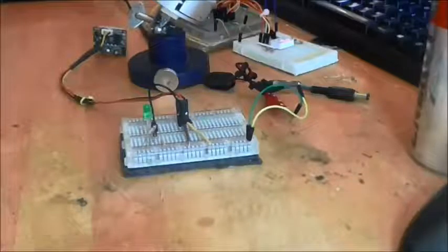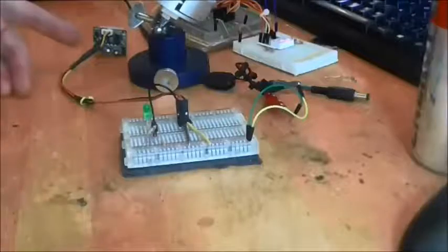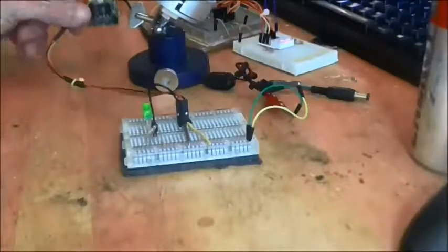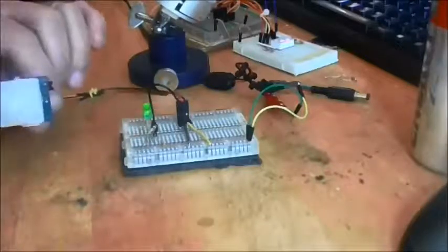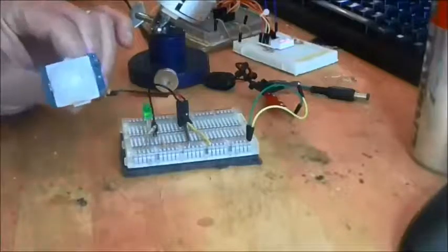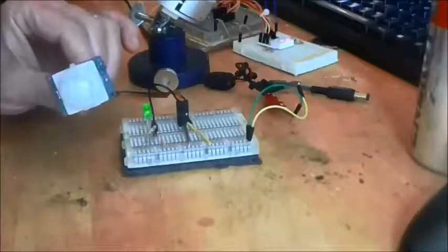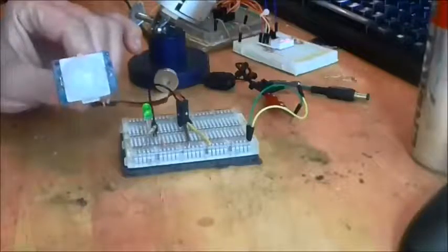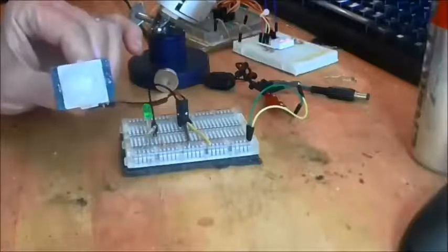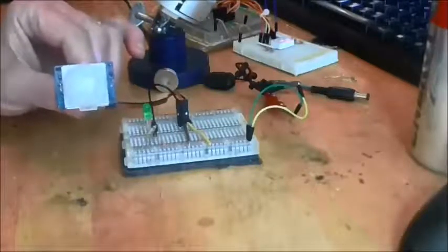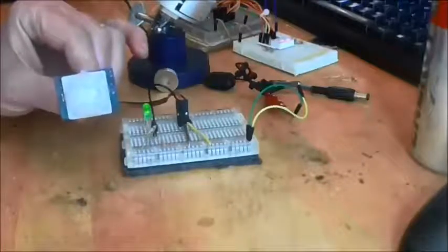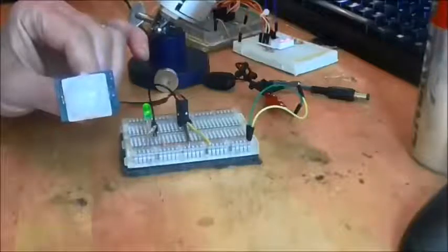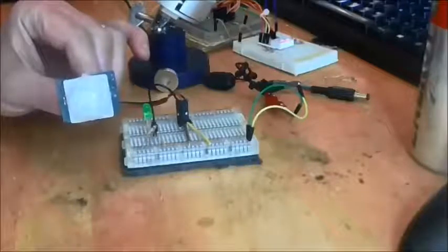So looking at the first of our input components then, we have a PIR sensor, and that's this thing here. And if we look at it, you can see what it does. When it detects movement, the LED goes on. We've got a Fresnel lens, and underneath there is a pyroelectric sensor, and that consists of 2 strips of crystal carbonate, and when infrared light strikes those 2 strips, they cause a potential difference between the 2.